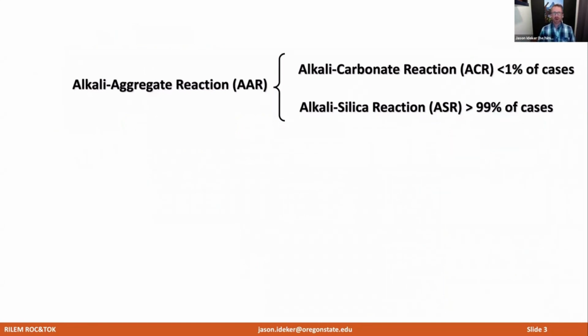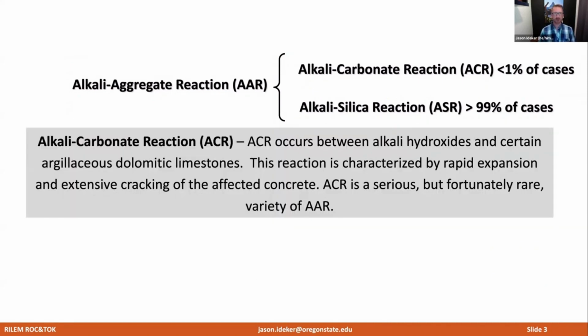So as I mentioned, alkali silica reaction actually falls under a subclass of a larger reaction called alkali aggregate reactivity. And ASR is responsible for at least 99% of all cases, if not even more. There's a second type of reaction, though, called alkali carbonate reaction, which is responsible for less than 1% of all cases of alkali aggregate reactivity in concrete.